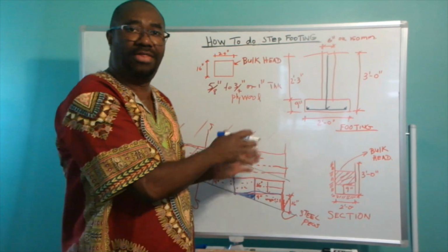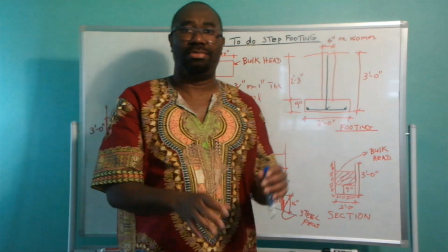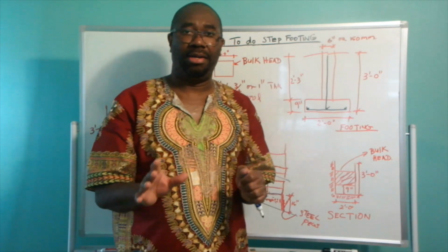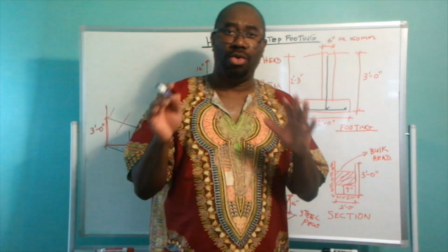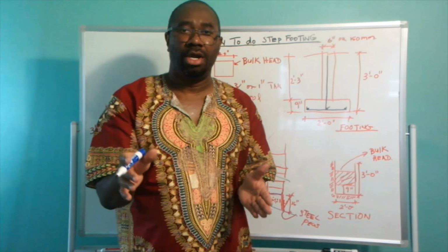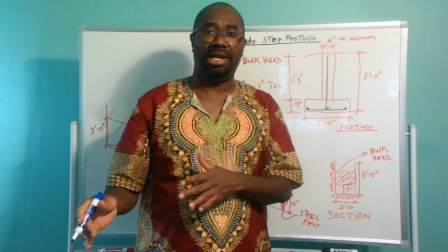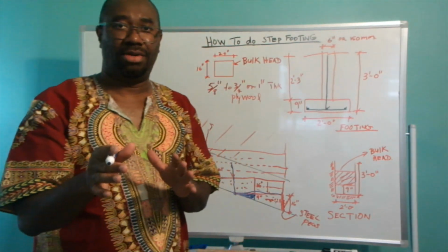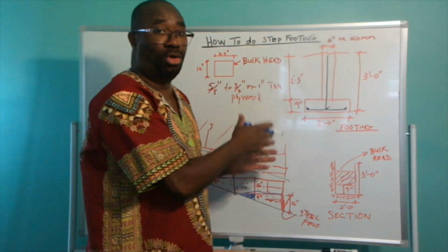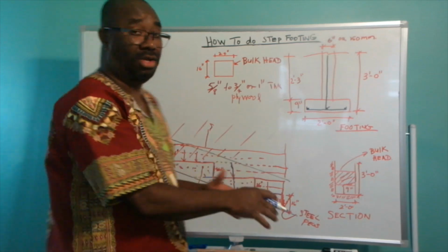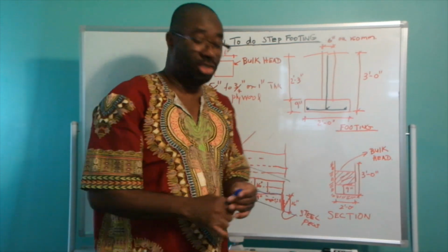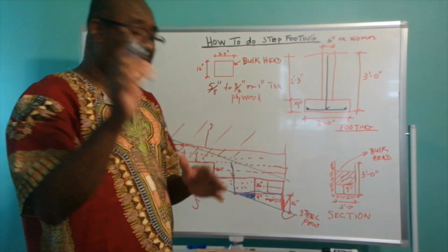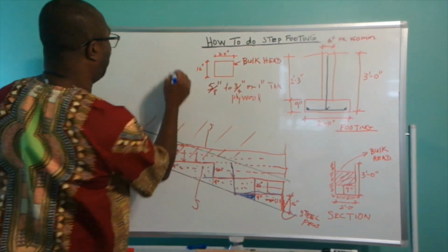And that part of the foundation is going to be subjected to cracking under the weight of the building, especially if you're doing a 2-floor building or a split level building with 2 additional floors on top of your split level. And a split level in most cases is when you're dealing with lands that are sloped. So I'm saying that practice should not happen. And what you have is this.